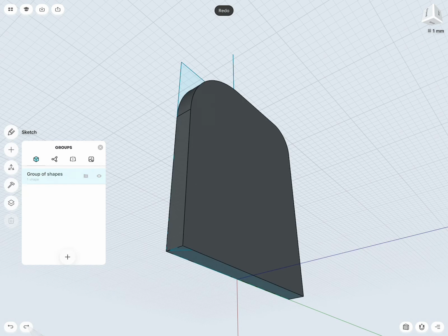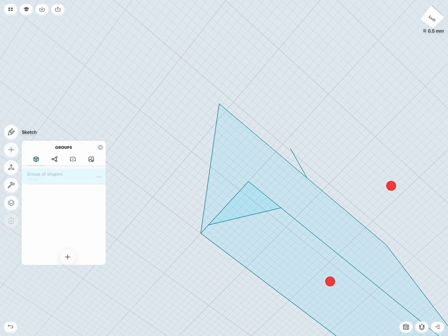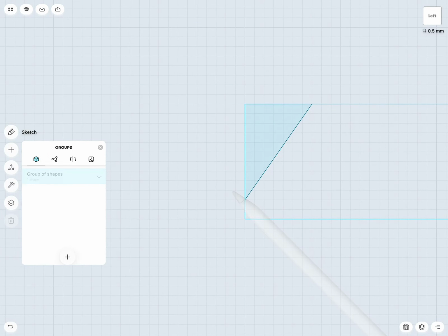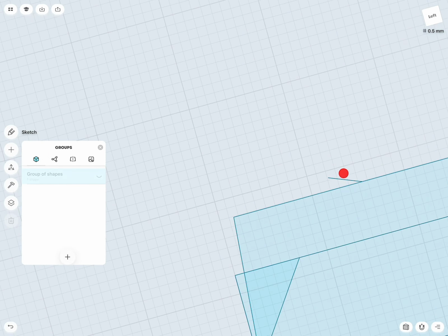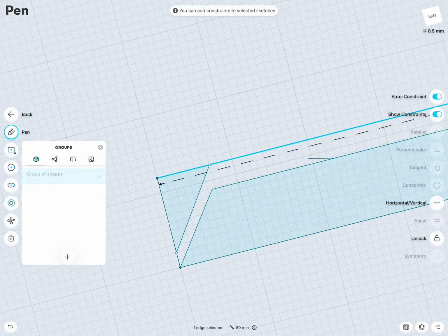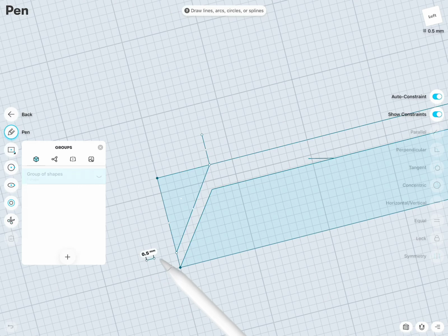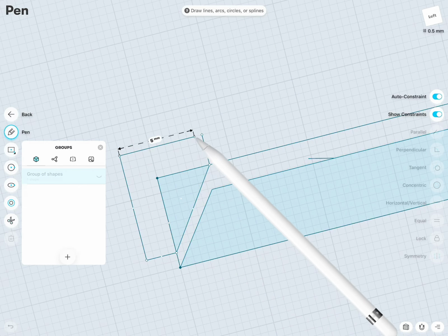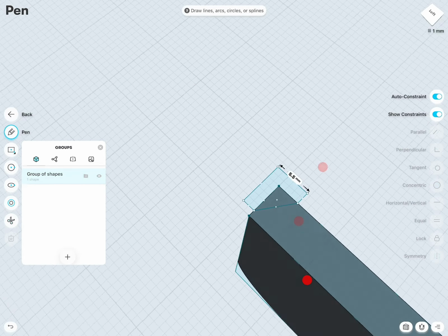Oh, that was one too much. Very good. And there we are. So I would like to go back to the sketch here, double tap there. And what we will do now is we will overbuild this a little bit. So I add a little bit of material to it. This way cutting surfaces do not intersect perfectly with the original object edges.